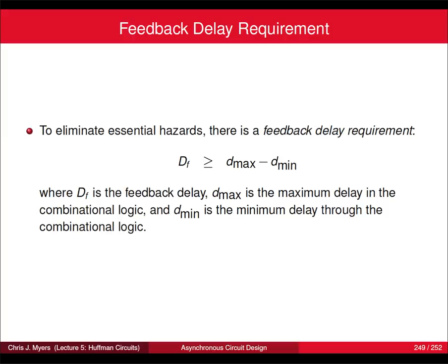Yeah, I mean, it's not like a specific delay that must be there, but what you do need to do is make it as small as possible because it affects your cycle time. So you do timing analysis like you do with synchronous design, but rather than computing only the critical path worst case delay, you also have to compute short paths, minimum delay, which I think sometimes you have to do in synchronous design because of hold time requirements.